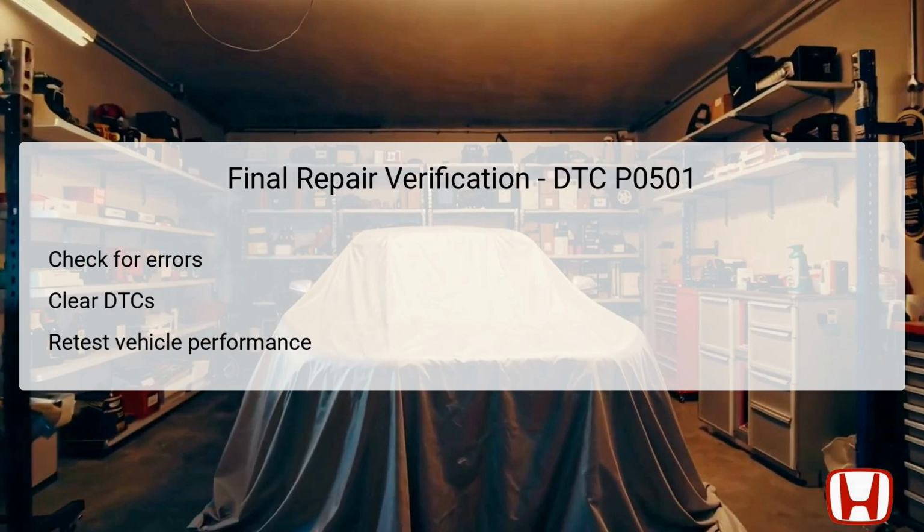After the necessary repairs or interventions have been executed, a final verification step is crucial to ensure that the issues stemming from DTC P0501 have been resolved. Begin with conducting a comprehensive error check to verify if any new codes have appeared or if the original DTC is still present following the repairs. Once this is completed, clear any stored error codes from the PCM, ensuring that it operates with a clean slate.